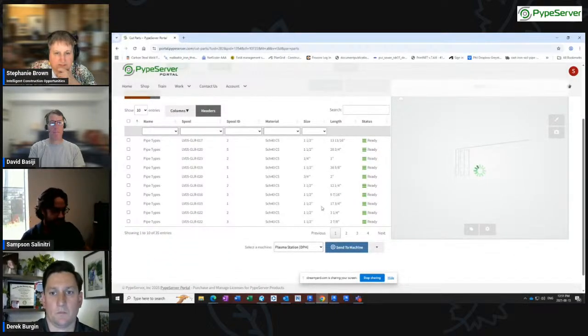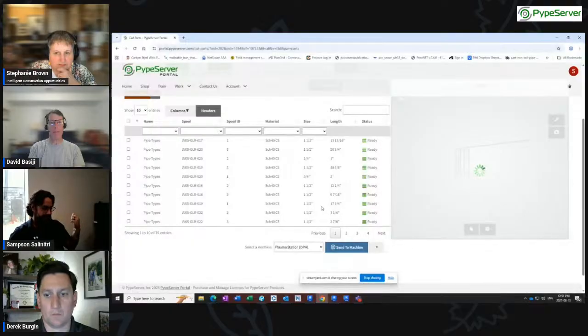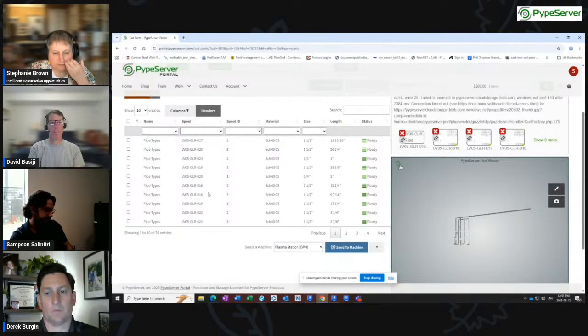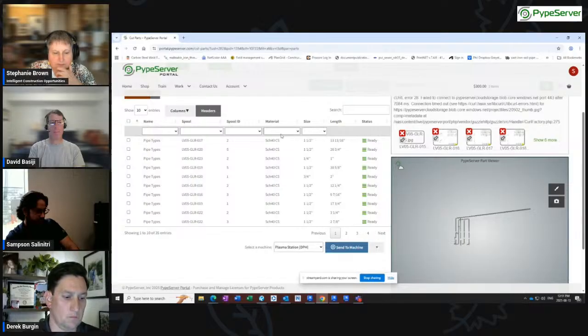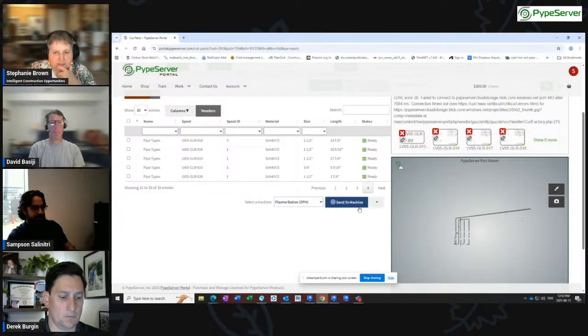So this is, again, right now the torch is still in VDC's hands. You wanted to know about roles. This is the last line of defense before it goes to the shop. So this is everything that's going to be sent out there. I'm looking to make sure that it's all reporting the right material, it's the right size, it's the right cut lengths, everything looks good. So I can go through all my pages. These are strictly reporting what is to be cut.